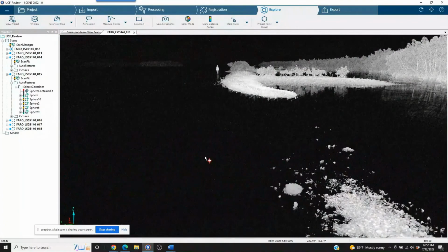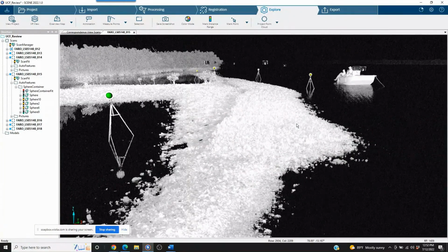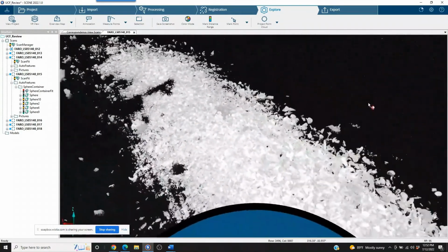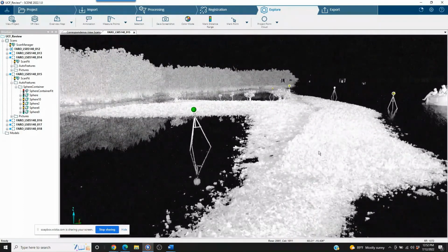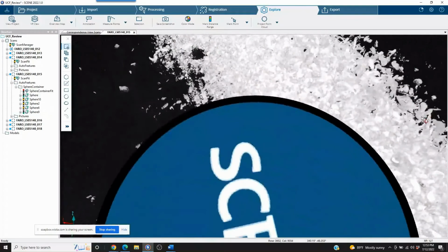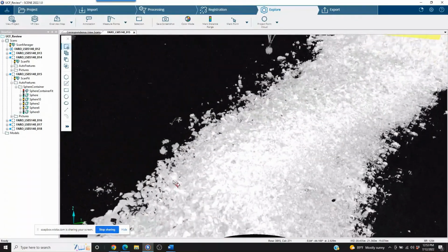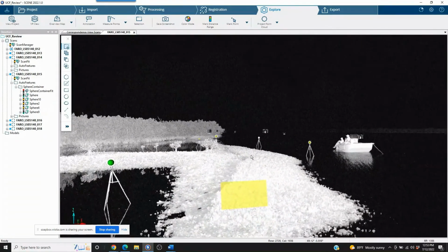But one of the other things that happen here is all the targets are on one side of the scanner and none on the other side. So, not the best placement of the scanner, I would say. You would have been better off having the scanner maybe in this sort of area, say here, and then you're going to get coverage this direction, but it would have allowed you to have spheres back here instead of having them all on one side.